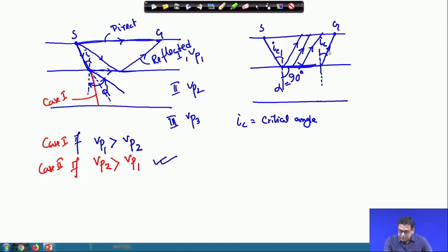But we have considered this path because we have placed the geophone here. If you place the geophone here, then we have to consider this path of the refracted rays. As we have considered this one, this is the geophone. So, now here there are three cases, three rays I have discussed.